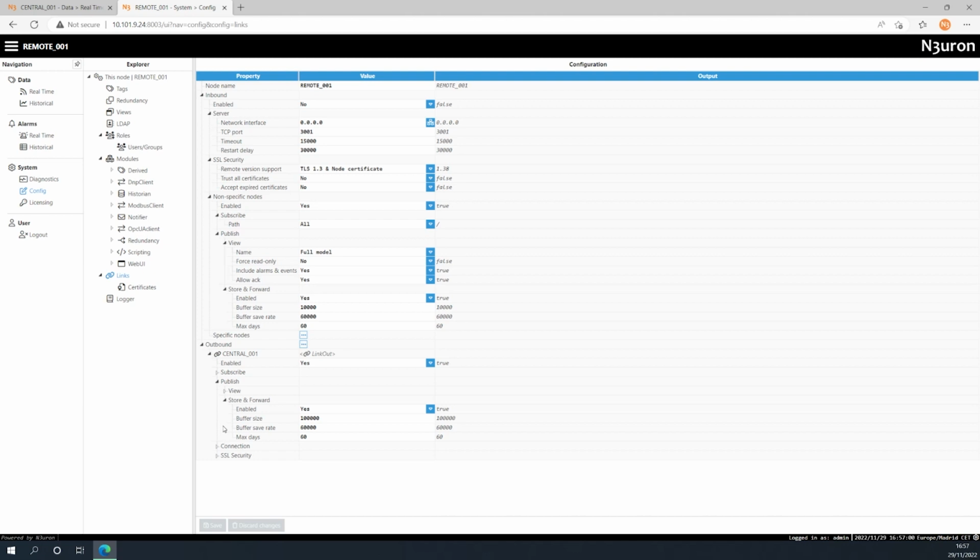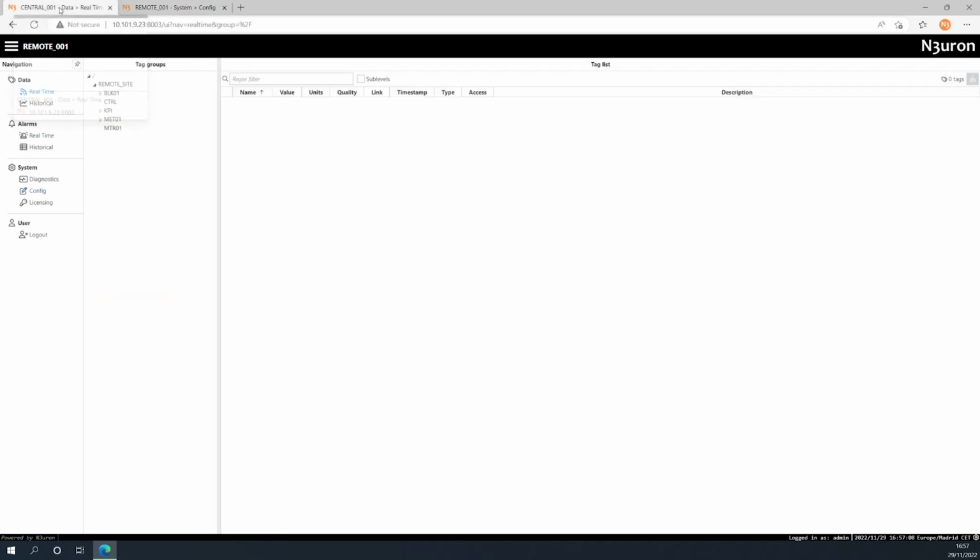To do this, we have previously configured a pair of nodes that are connected via link, in which we are simultaneously historizing some variables in both a local and a remote historian instance. These tags are also being published to the central node by the remote node. The store and forward feature does not require data to be historized, but we will use it here anyway, because it will allow us to demonstrate how the mechanism actually works in a nice visual way.